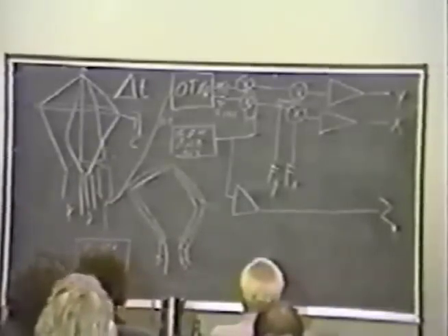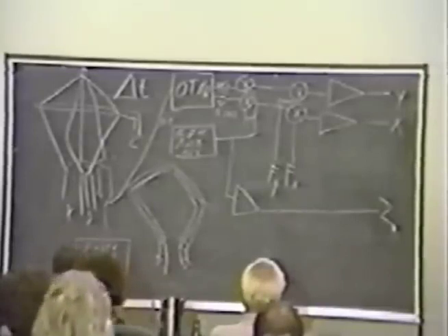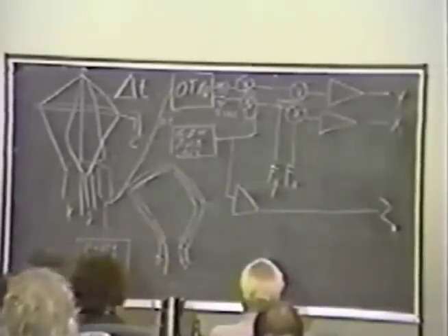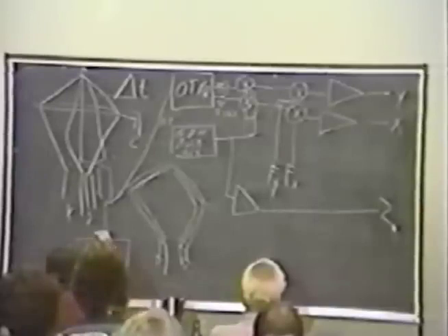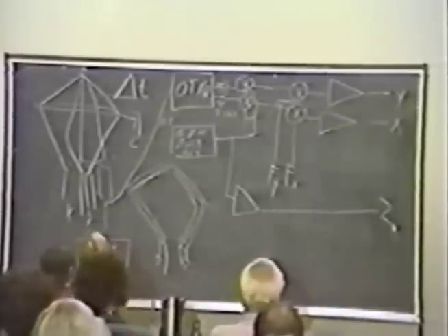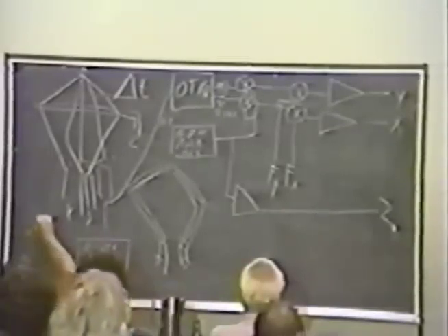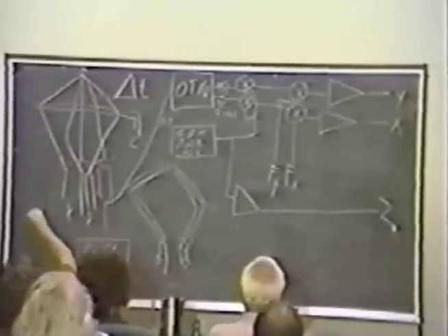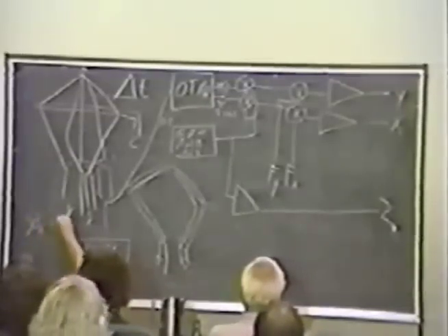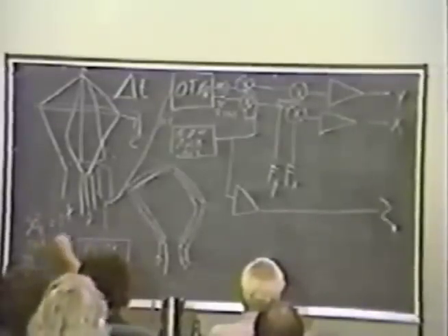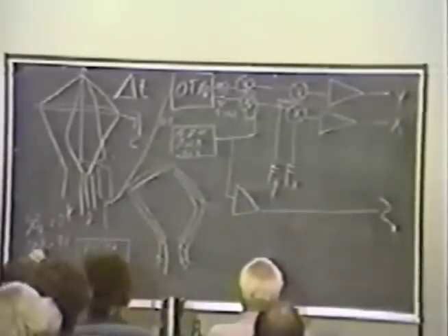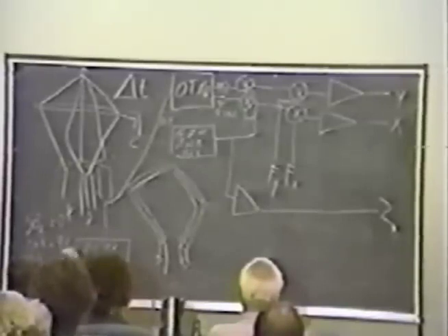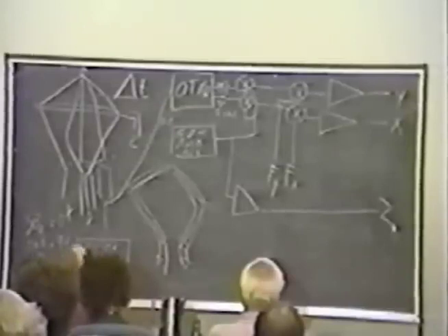Now, this is a very unique radio transmitter. It's ISB. Any of the hams know what that means? Independent sideband. This is a double sideband suppressed carrier transmitter. But lower sideband is at 0 degrees. Let's put it over here. Carrier equals 90 degrees. Upper sideband, upper is 180. This is called a bi-quad, bi-phase radio transmitter.